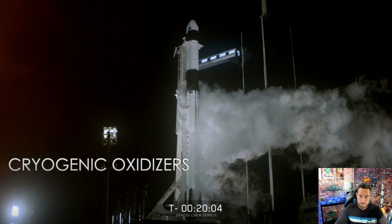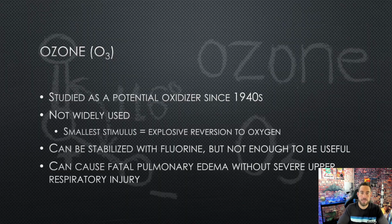So whenever you watch a Falcon 9 launch, you'll see all these clouds that are coming off of it. People have thought, oh, it's on fire. But that's totally normal. Liquid oxygen is a cryogenic, so think about it as having a low boiling temperature. So it boils off very easily, and it's hard to keep it in the tanks. You have to have this continuous resupply going. And in this continuous resupply, it generates all these huge clouds that come off of it. So whenever you see something creating major clouds like this, it's a cryogenic that's going into it.